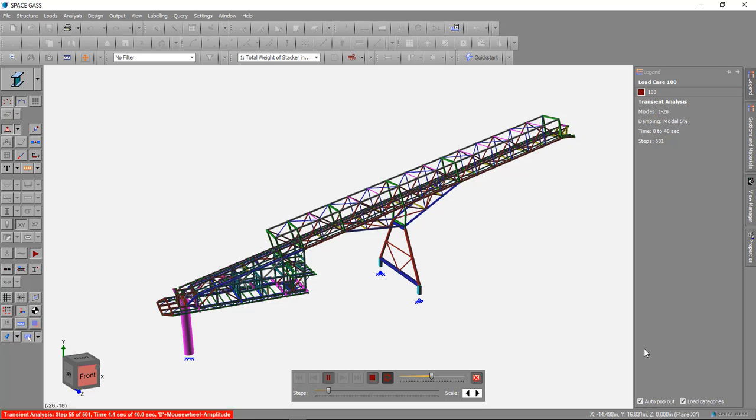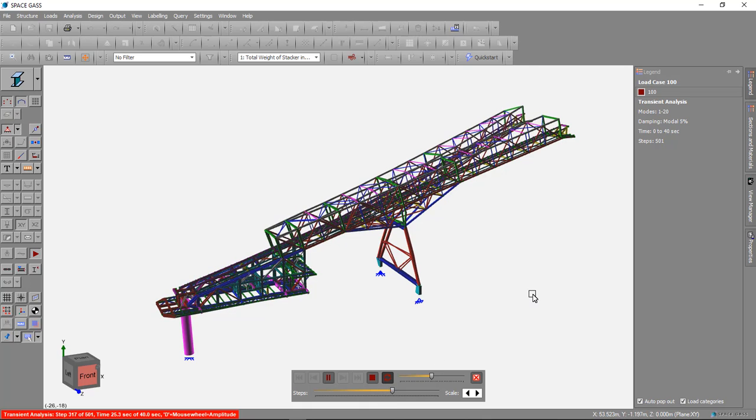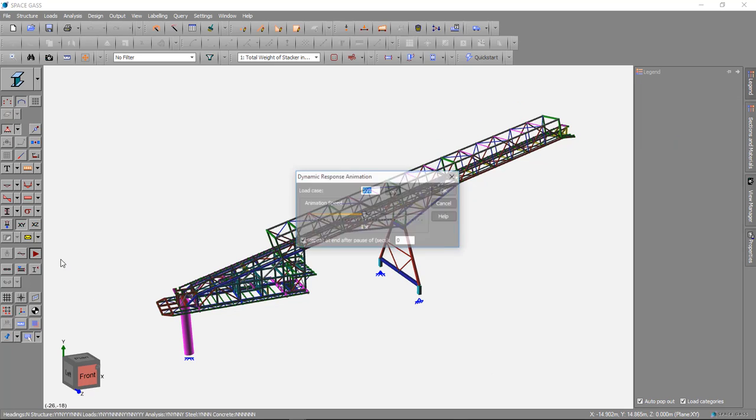So this is an example of what I mentioned before about expecting to see something but nothing's happening, and it's probably because the displacement scale is not high enough. So I'll just hold down the D key and rotate the mouse wheel forward a little bit. It's just in the constant velocity section here at the moment, so there's not much happening. Just exaggerate the scale a bit more. And maybe just start that again just so that you can see it properly.